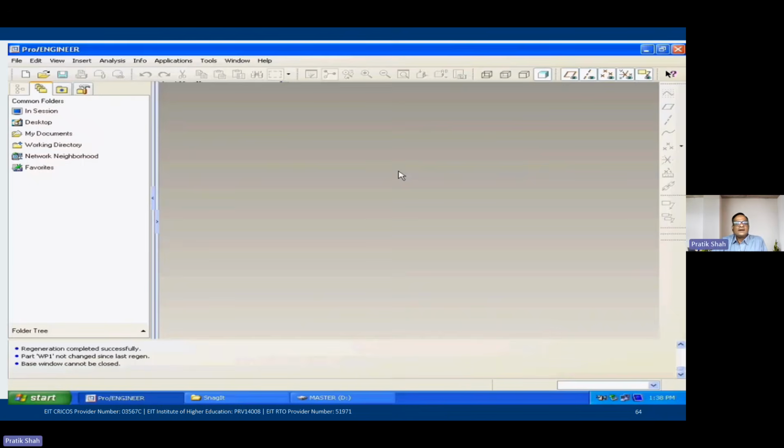So now what I am doing is creating a tool path. I am making the system understand that this is my machining path. This is how my tool should move and remove the additional material. Now comes the process plan. As I talked about, the process planning phase involves identifying the machine sequence, the machine tools, and the tools which are to be used. So I am specifying the machine 0. I am saying that this would be my 0 point from where the machining is to be started.